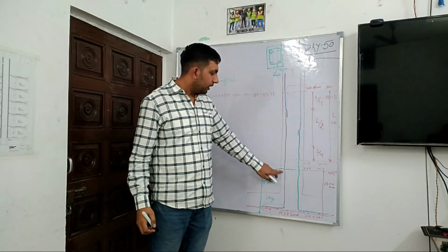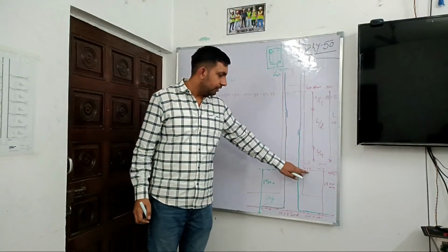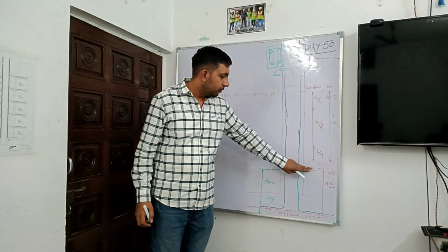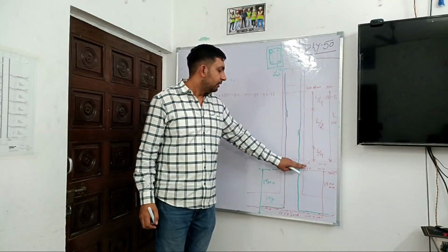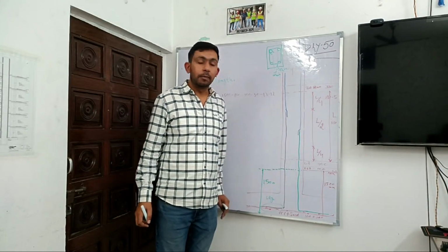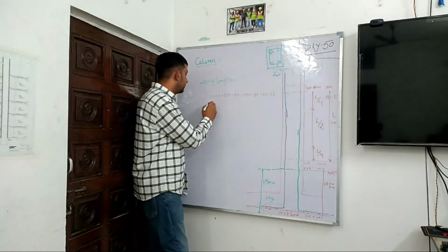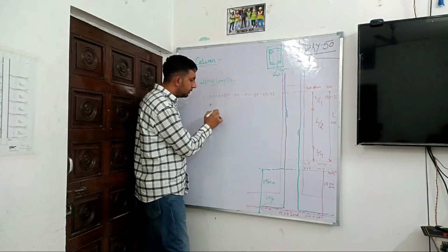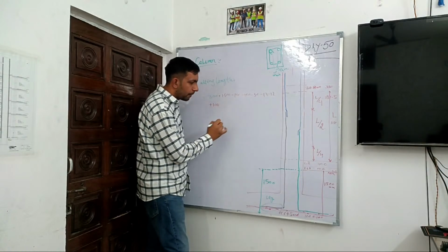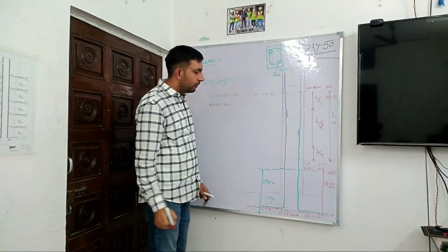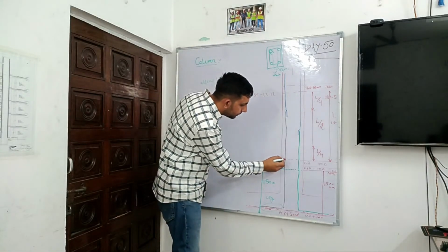And from this point, we can see in this section drawing of the column that there is a brickwork of 100 mm and ground width of 300 mm. So we will add this also in our main rod cutting length, 100 mm plus 300 mm. So far we have reached this point.